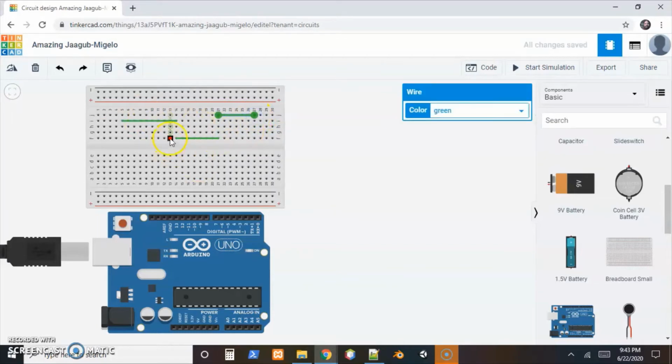We just bring some electricity into one of these rows, then go through a component or a wire to another component or wire, from one row to another, and connect things that way. So let me delete these little wires here. Basically a breadboard is just a bunch of plugs, nicely organized and labeled so that we can plug things up and give it a try.